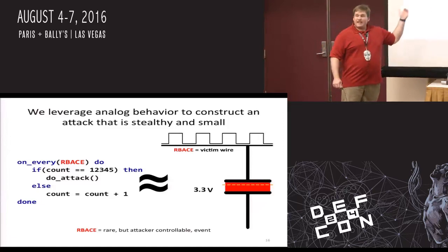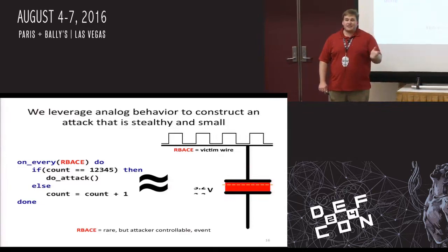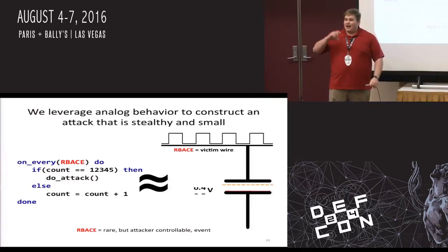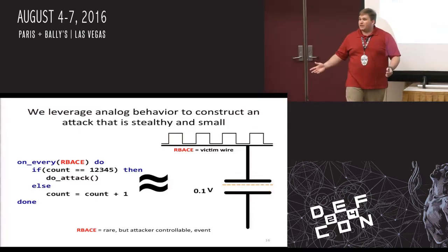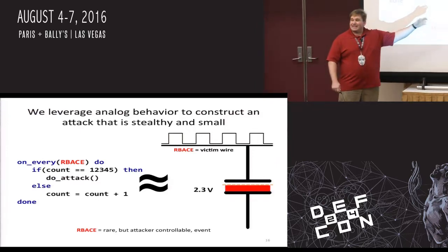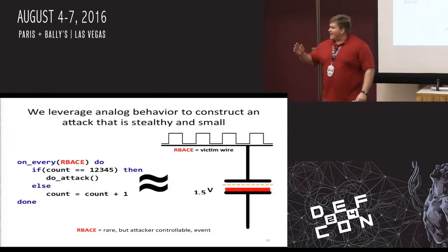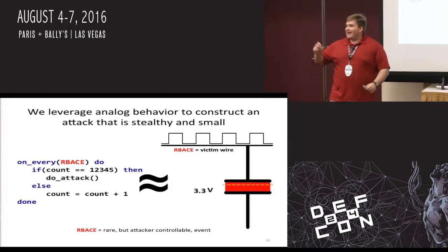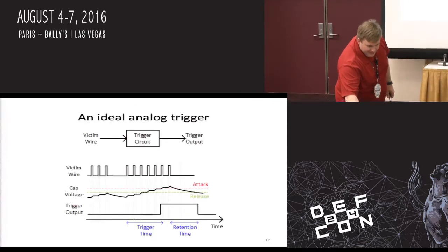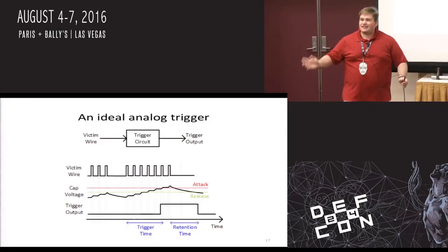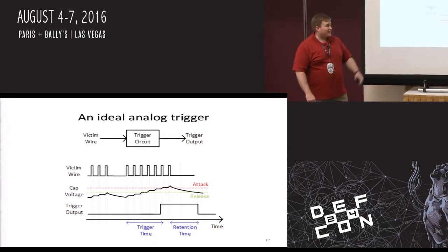So you can see here, these are almost analogous, except the capacitor is actually more complex because capacitors leak. If you charge up a capacitor and don't connect it to anything, eventually you'll come back to it, and it will have 0 volts on it. It will lose all of its charge. Well, that's kind of a leaky bucket counter, which has a great impact for us because that means you can get what they call spurious activations. So you put some charge on there accidentally, and it will forget about that the longer in time you go. So that's the high-level observation. The capacitor acts like an accumulator. So the rest of it is just how we actually implement that to get the effect that we want.